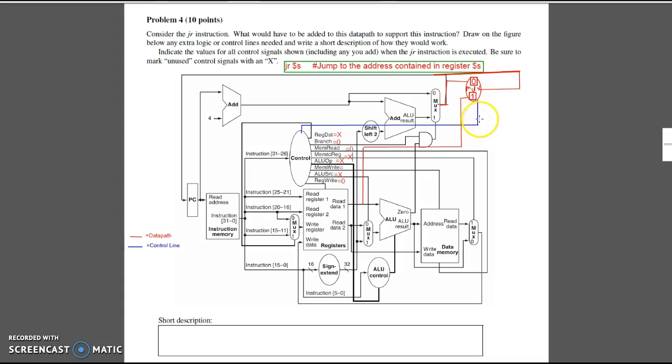Now, one of the inputs we must take, of course, from our read data 1 that we pulled from, and the next input we take from the output of this old mux. So basically, it would choose which one to read, so that way you could still increment PC by 4. You could still branch, or in this case, still do the jump register instruction here. It would just depend on what the control signals were set to.